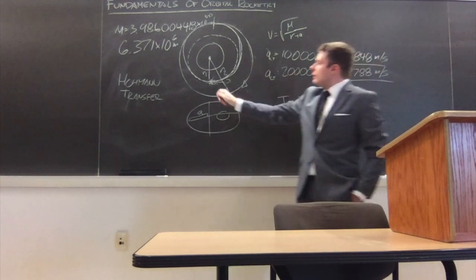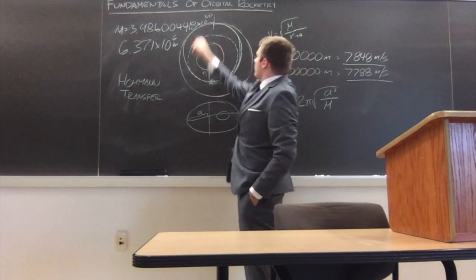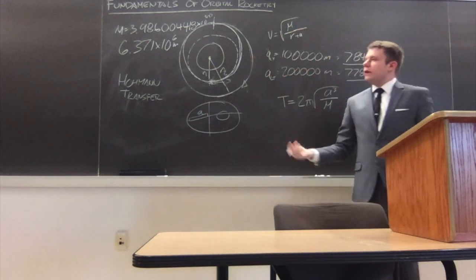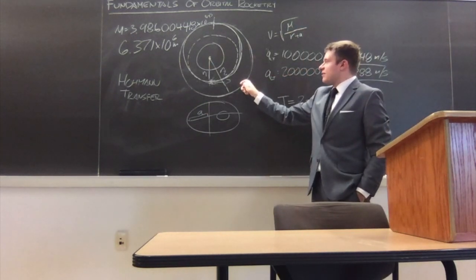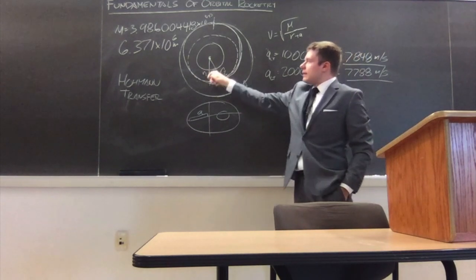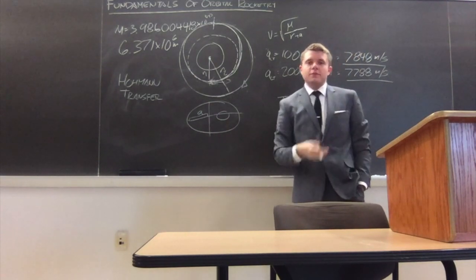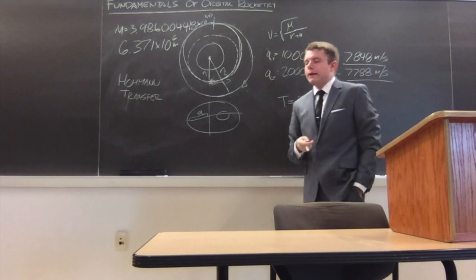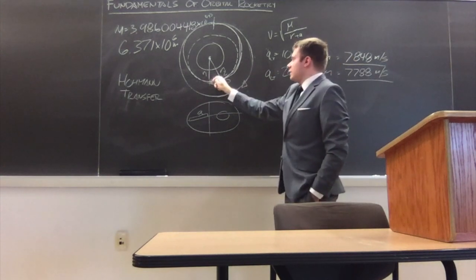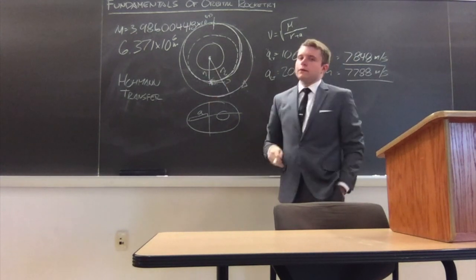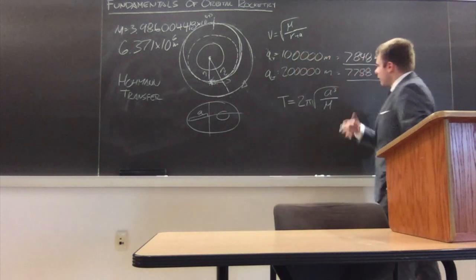So, we pick ourselves up to apoapsis. We need to know when to do it, and we can back calculate the position that this spacecraft needs to be in order to meet it. And we can also introduce the concept of the phase angle. The phase angle being what angular position difference do we have to be between us and the target in order to actually meet it. So we look at this equation.